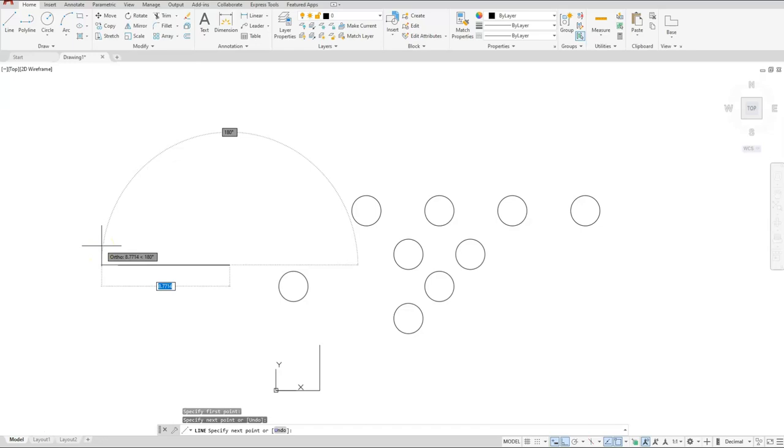and I say, okay, next I want to go up 5, I have to make sure that I get the preview of that line going at a right angle. I've seen some people where they'll have it still pointing this way, and then they'll type 5, so that line is just going to grow by 5, but they're not getting the angle to come up. So you have to use the preview.